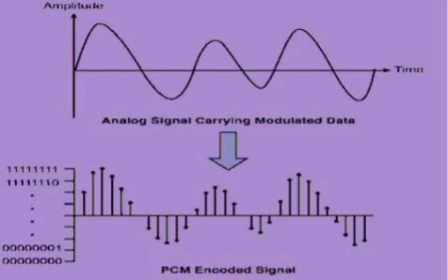The process x of t is called wide-sense stationary if the following conditions are satisfied. Mx of t equal to expectation of x of t is independent of t. Rxx of t1, t2 depends only on the time reference tau equal to t1 minus t2 and not on t1 and t2 individually. If Mx of t and Rxx of t plus tau, t are periodic with period T, then the process is called a cyclostationary process.